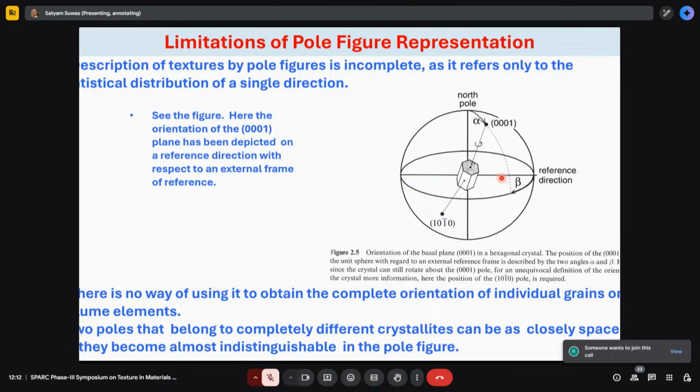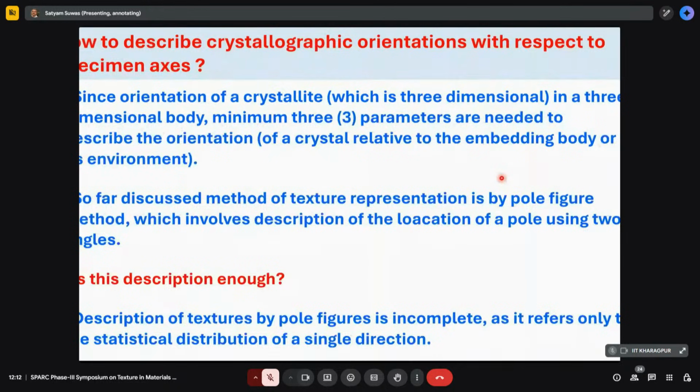Similarly, here there are a countable number of bodies, but in a polycrystalline material, there are countless numbers of crystals, or a large number of grains, and each grain participates in the diffraction. So therefore, you will get diffraction output from each one of them. If there is such kind of ambiguity, then you will not be able to represent texture properly. So that indicates projection methods are not the best ones, though they are very good ones to give an initial indication of texture.